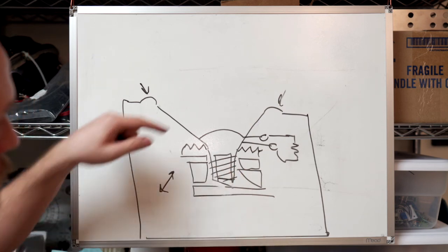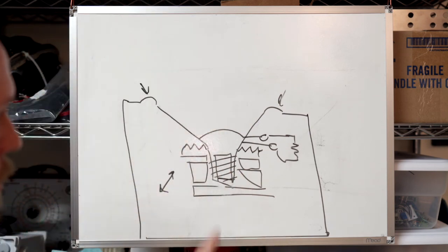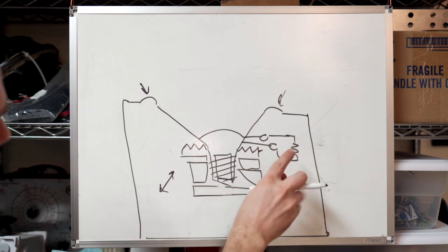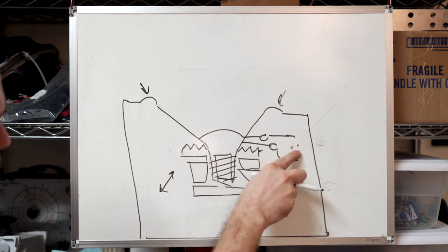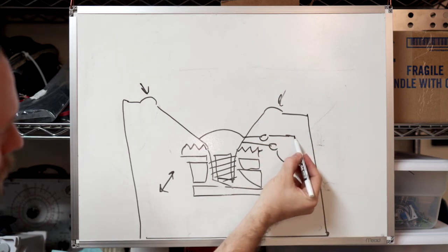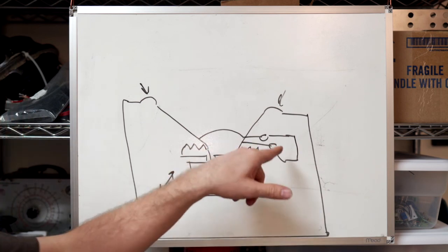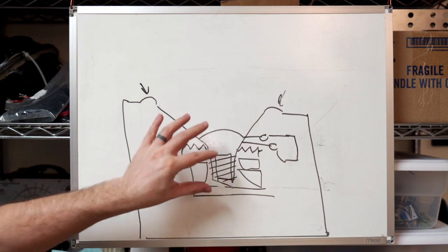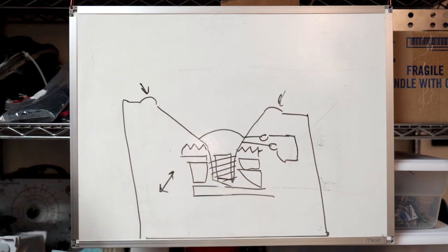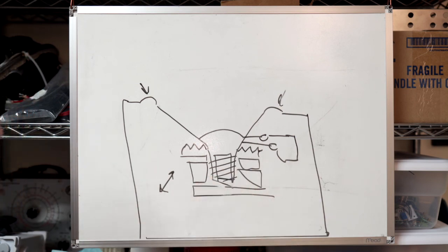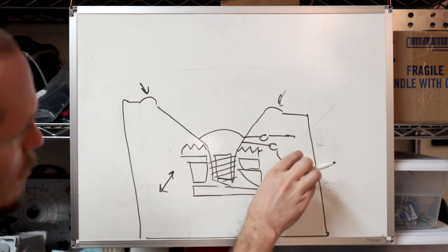So I don't know if you're aware of this, but if you push on a speaker, you generate electricity this way. And that's sort of back electromotive force, I think is what they call that. And if your output impedance is sufficiently low, like let's say it's something approaching a dead short, it just dissipates that right there at the amplifier, and the woofer does not resonate at all, just like we sort of showed when we shorted the outputs of those woofers, right? So if your output impedance is higher, you can have a little bit more ringing.